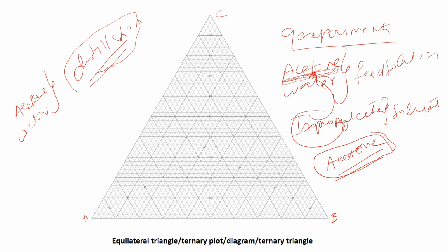So distillation, that time we will know how to separate this type of fluid mixtures, but it's going to be very expensive, due to the temperatures involved. Water has a higher boiling point and so on. But if you use acetone and isopropyl ether, it's very easy to separate acetone from isopropyl ether.